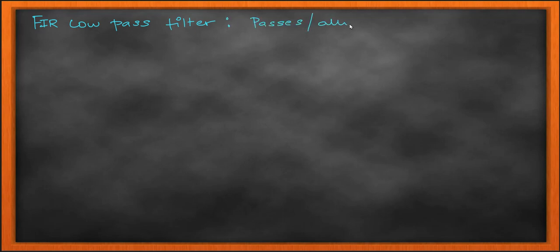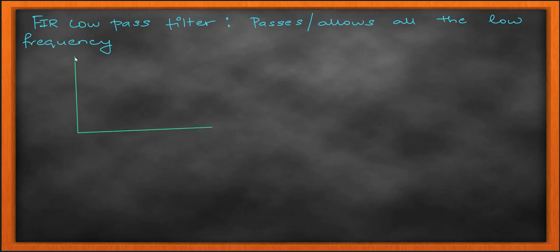There are 4 standard filters that are very common, that you see whenever you have a DSP. So it is very simple. In communication, we use the low pass filter because our audio signal, the voice that we are using, is a low pass signal, or a low frequency signal.